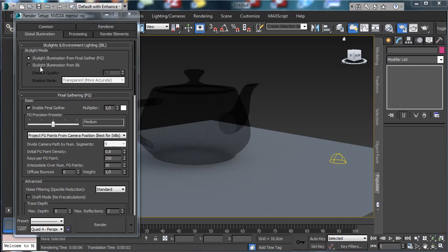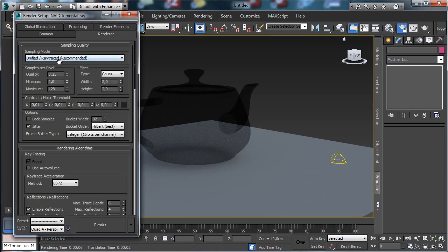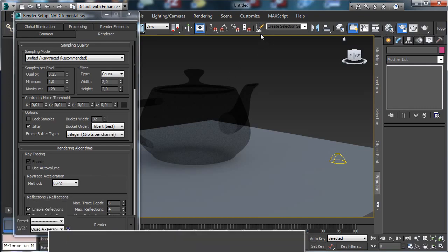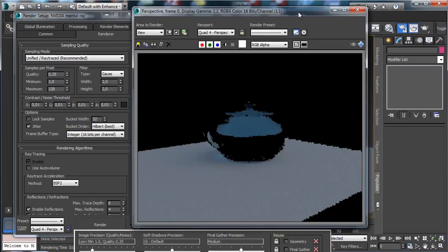And it is usually faster than the standard kind of render. And you see that there we essentially no longer have the minimum and the maximum samples for the anti-alias, but we have the quality level, and then we have the minimum and the maximum. In this way we have the possibility to speed up the rendering,